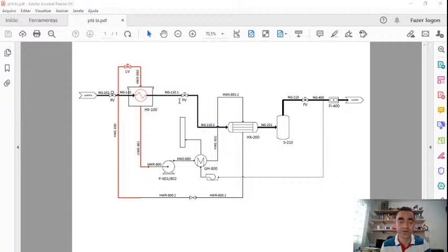depressurize this gas in the first step, because it is at high pressure. After that, because of the depressurization, the temperature goes down and I can have condensate in this process, and because of that I have a heating with a heating media, and a separator vessel to guarantee that I don't have any kind of condensate or liquid going to the customer.